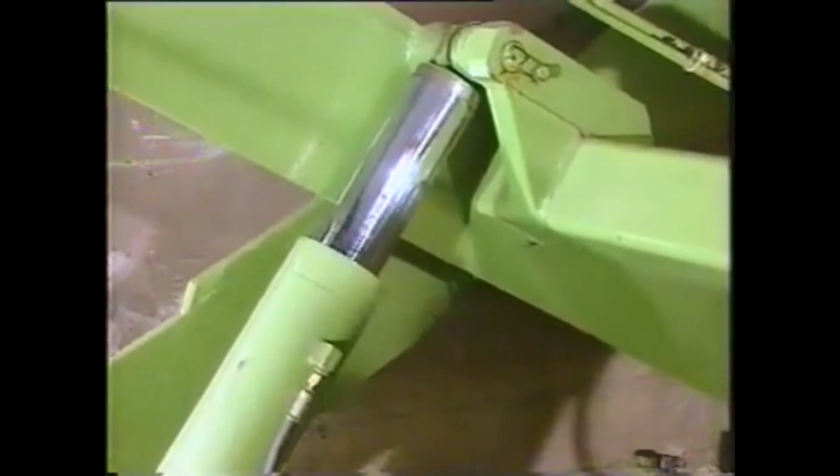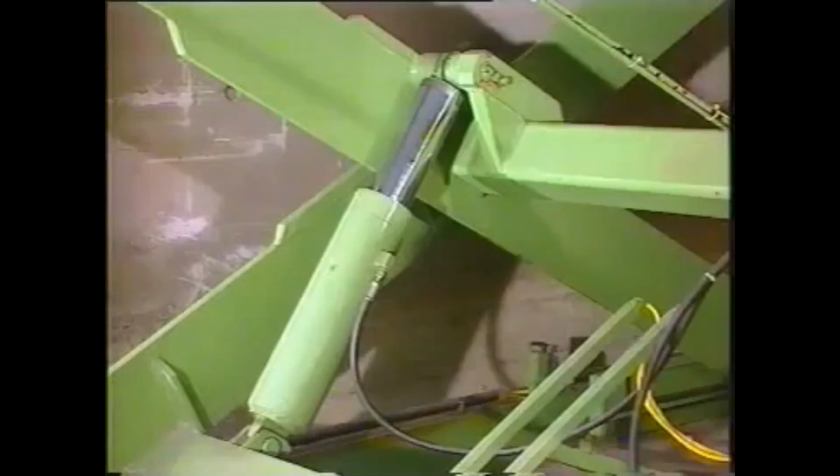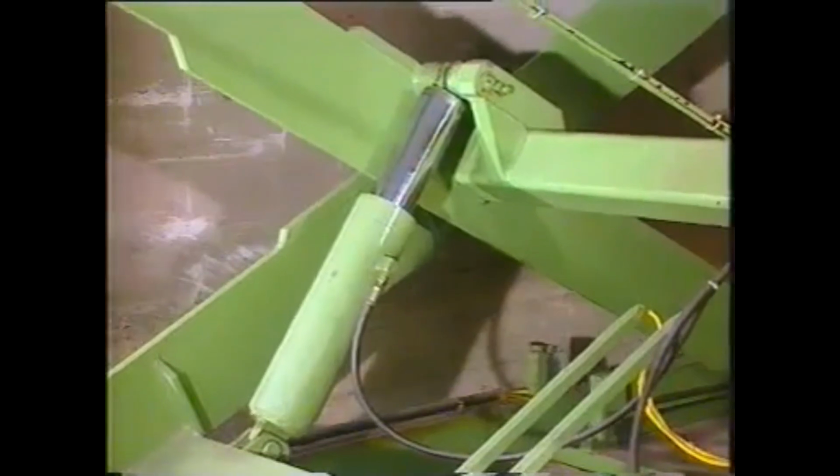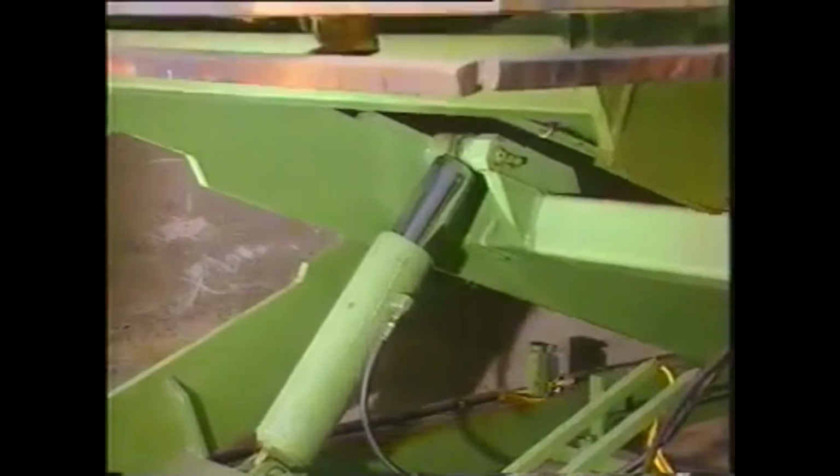The single-acting cylinder in this scissor-type elevating platform is a so-called plunger cylinder. Here the piston and rod diameters are the same. This design is extremely bend-resistant, which makes it particularly suitable for moving heavy loads. This is why plunger cylinders are often used in platform lifts.